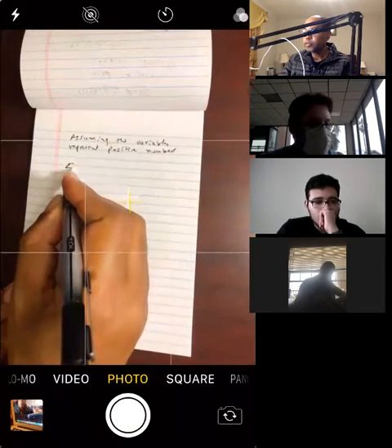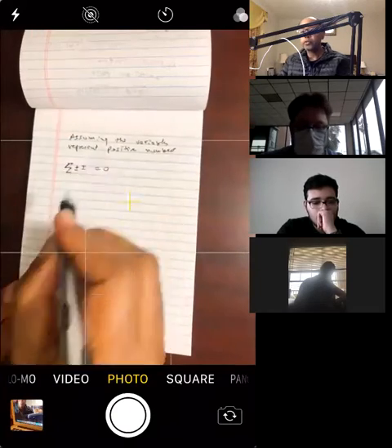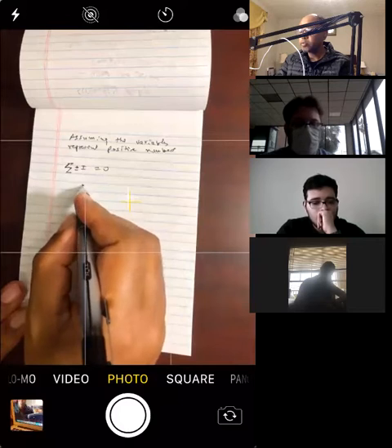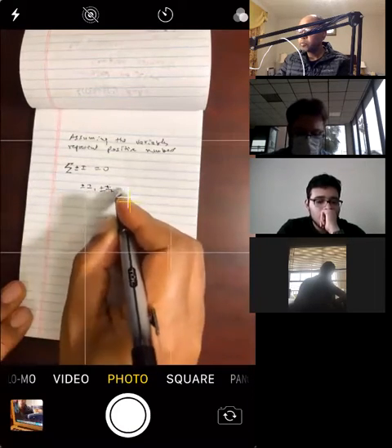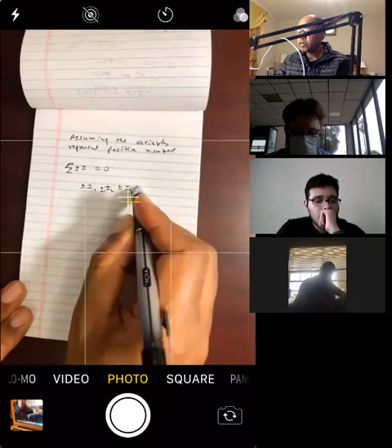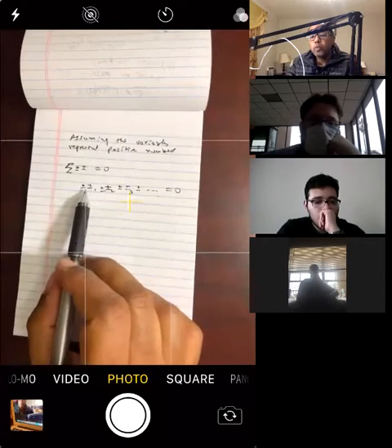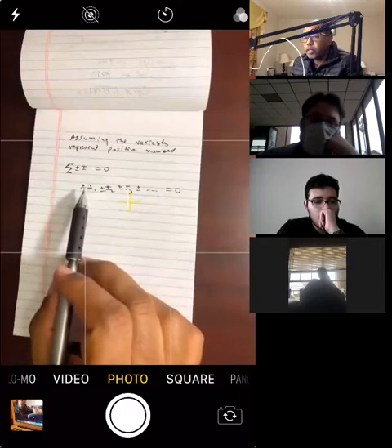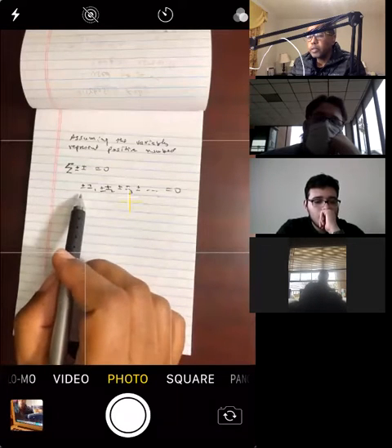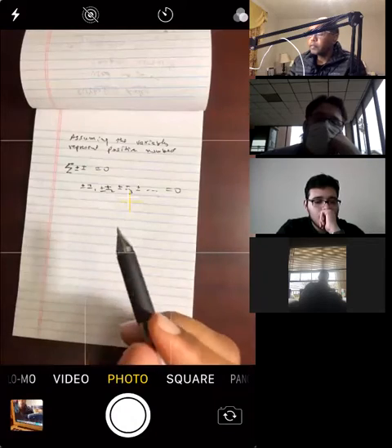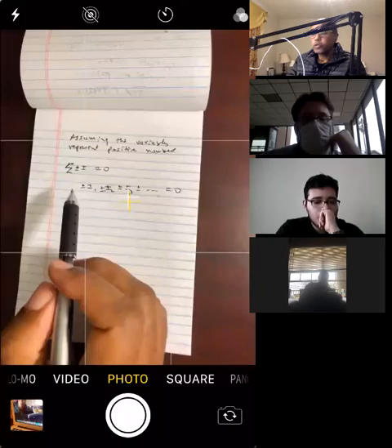So if you assume the currents are positive, then you have to put plus or minus I over here equals 0. Or if you extend it, you can say plus or minus I1 plus or minus I2 plus or minus I3 and so on, equals 0. And then you pick the plus or minus depending on the same convention. If it's going in, you pick the plus sign. If it's going out, you pick the minus sign. So we're going to assume the variables are positive, and then we introduce the negative and positive signs outside.